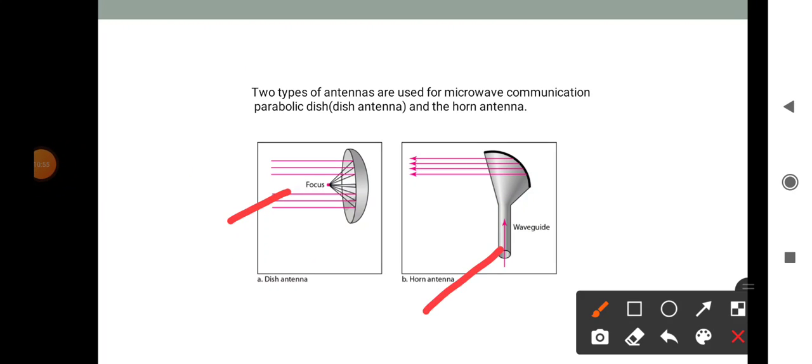First, the dish antenna is one of the most widespread of all microwave antennas, and the dish is not actually an antenna but serves as a reflector, and it must be driven by a radiating element at the focal point. This radiating element could be a dipole or horn radiator, and it is basically based on the geometry concept of the parabola.